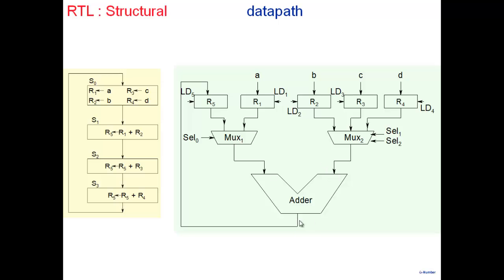And then it gets added up and appears over here. In this case, similarly, the select signals have to be appropriately applied, so the appropriate data appears here and gets added here. And who's going to decide which select signal comes? From the controller. The controller will say, in this particular state, send this particular select signal. And so that is what will happen in the data path here.